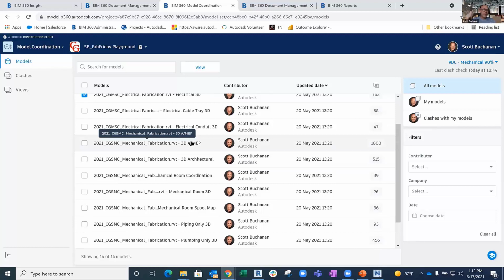Okay, so for my Navisworks users, think about if you were in your Revit project and you had 3D views predefined in your template, and you called them Navisworks exports, and you would export out an NWC for each of these different areas, right? Whether it's discipline only, level only. Like, I don't have these broken out by level. I should.